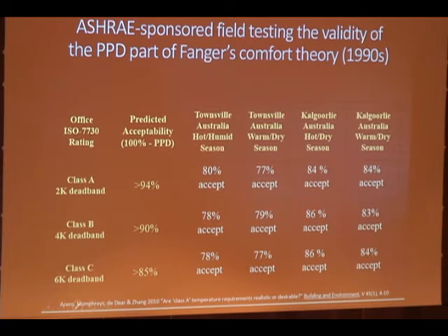The PPD stays pretty constant. I shouldn't say PPD, I should say the observed percentage dissatisfied stays pretty constant from Class A to Class C.